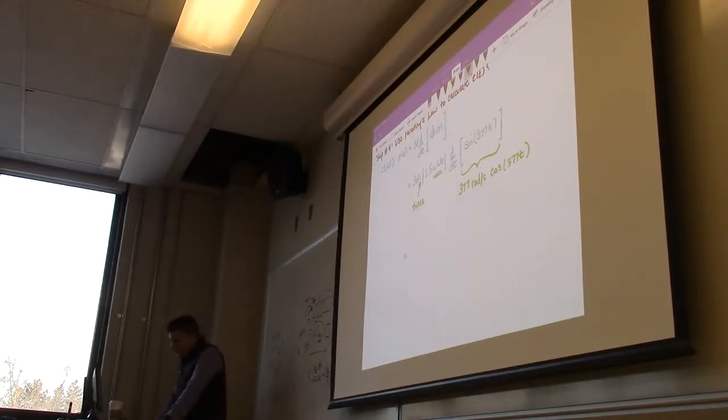Okay, so what we need to do is to make sure that all of these work out together. So when we multiply all the numerical values together, we end up with 169.65 cosine of 377t. And then the units we have are webers. We have radians per second. And then we have the turns.